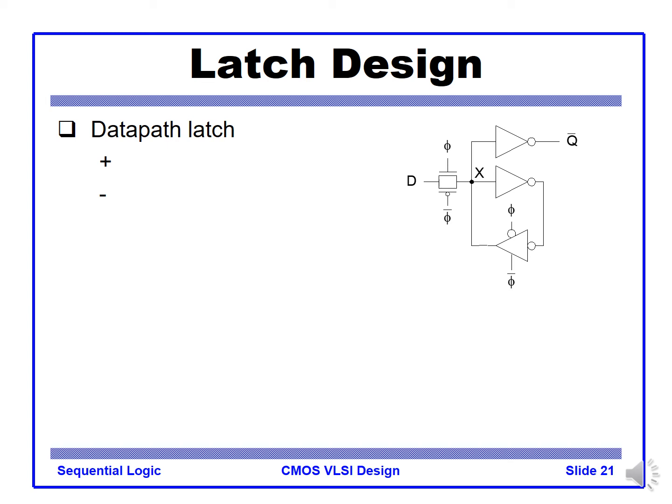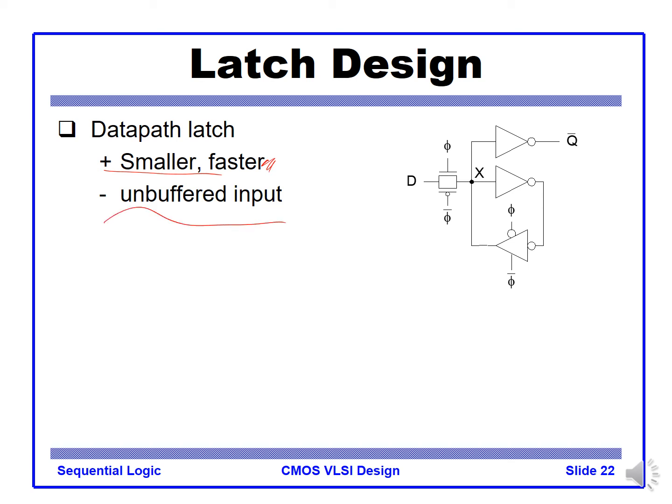You can simplify the latch design by eliminating the input inverter there, but you get the inverted output. It becomes smaller and faster, but the input is unbuffered.